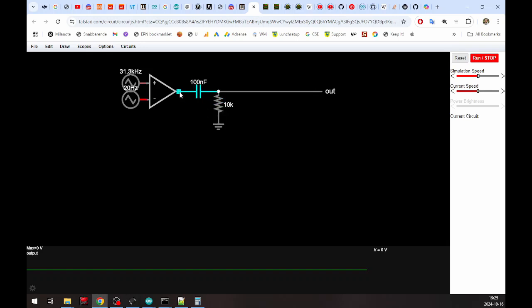this is an RC high-pass filter. This is not what we're going to use at all. That would really take away the function we want. We want an RC low-pass filter. Resistor in line with the signal and a capacitor to ground.